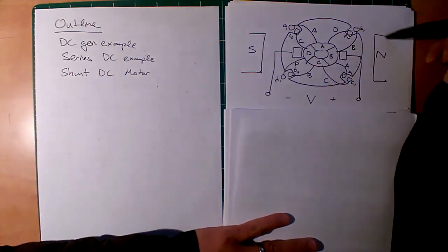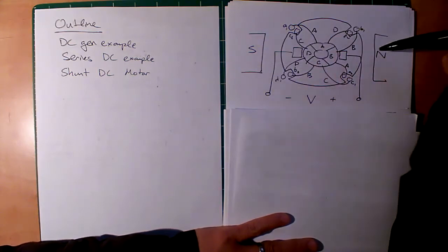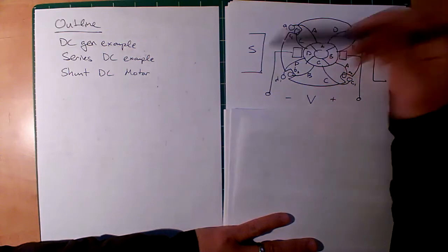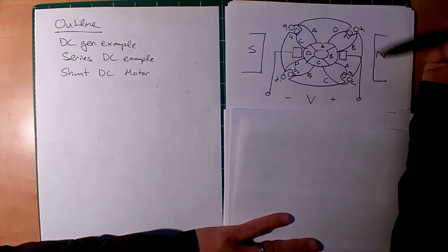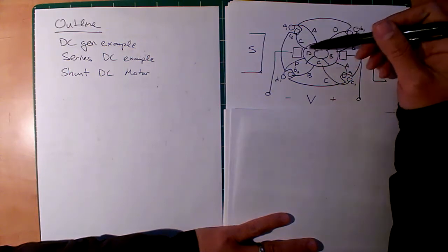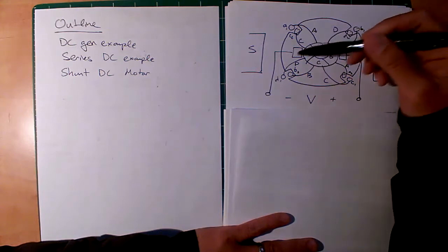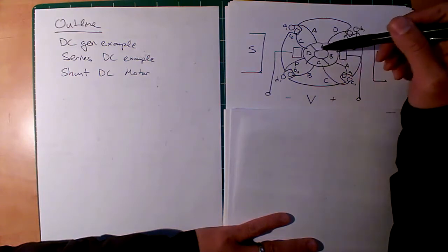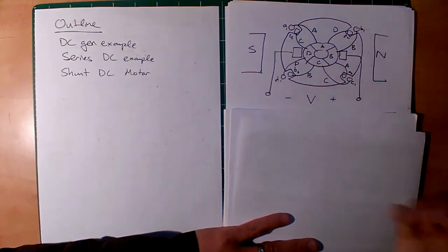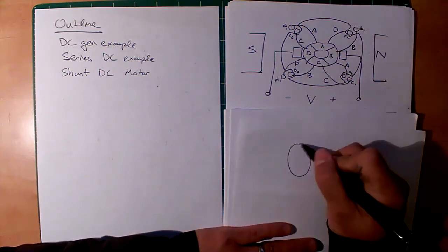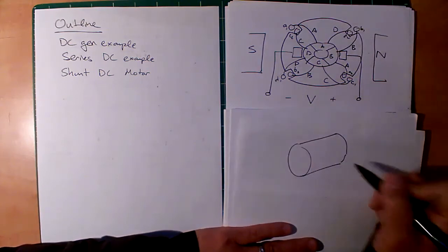So what we have here is your external magnets. They could be electromagnets or permanent magnets, and it's creating a magnetic field going from north to south. That's one of the 7 fundamentals. And if you look closely, what you see is the commutator and the brushes. And this commutator is attached to these wires. This is actually a design that you guys could do for your DC motors.